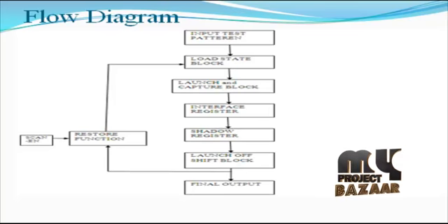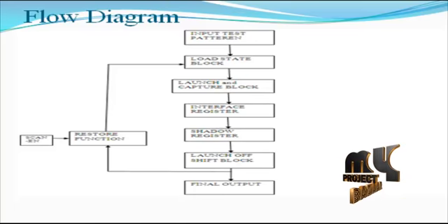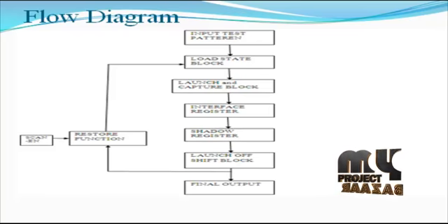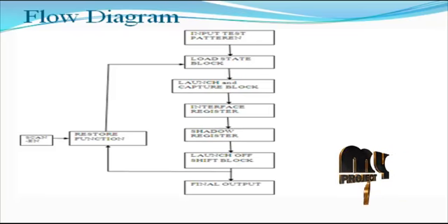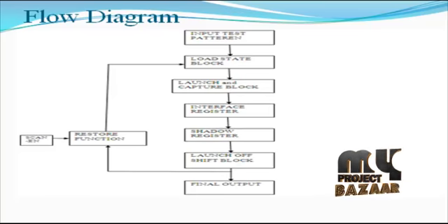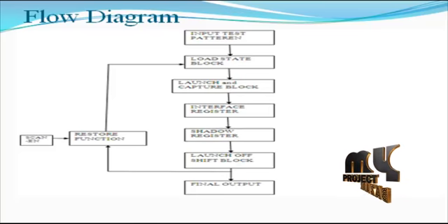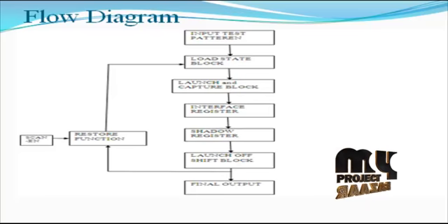Next, we will see the flow diagram for the product. First, the input test patterns. The input test patterns are applied to the S9234 benchmark circuit. The S9234 benchmark circuit is a standard architecture. It's a type of combinational architecture, mainly based on the NAND gate function. This architecture produces the input test patterns.